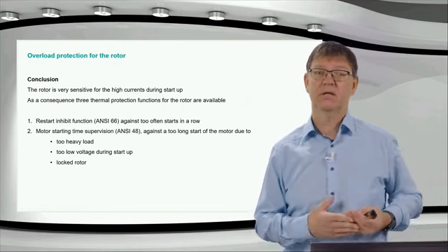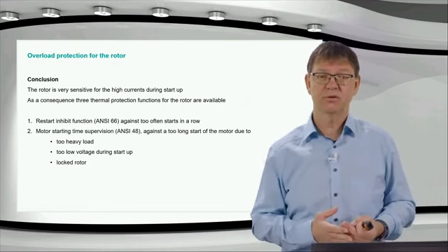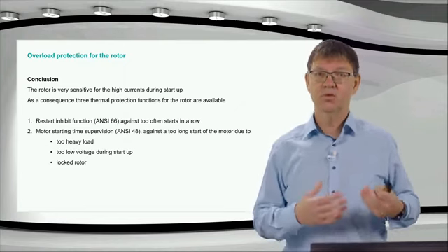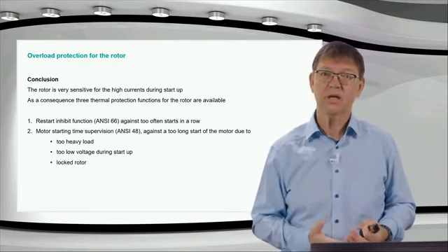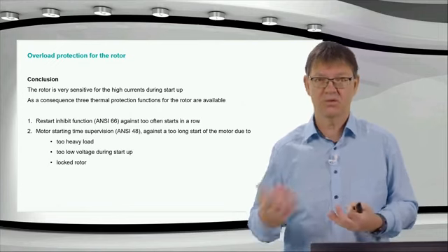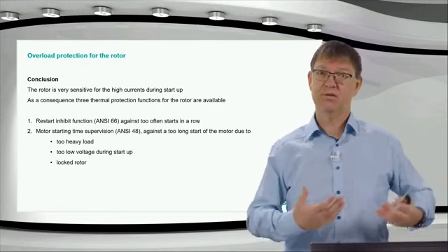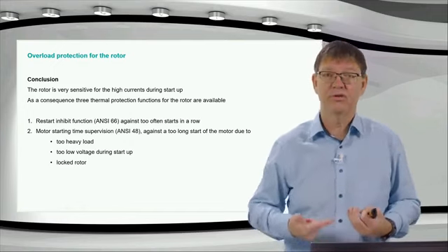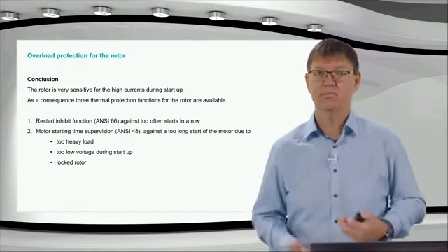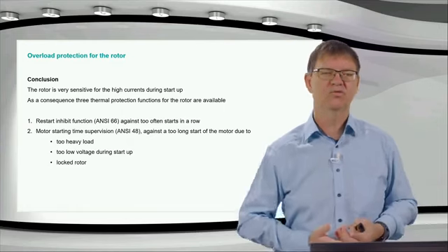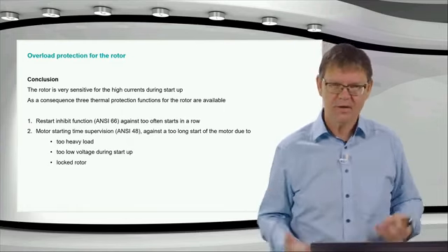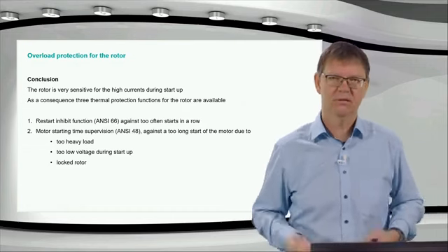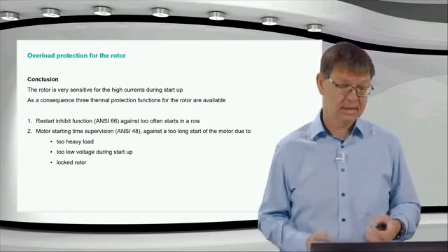And with the motor starting supervision, time supervision, the ANSI 48. This is against a too long start of the motor, which can happen, for example, if the load is too heavy, if the voltage is too low, so that the torque cannot be anymore created by the motor to start up the load, or if you have a locked rotor situation, that something happens in the machine and you want to start a motor and the rotor does not just start up at all.